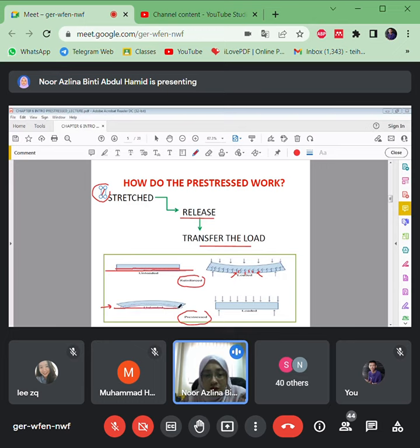We couldn't see it obviously by our eyes, but actually it has a slight deformation from the midspan to the ground surface. It's upward here because of the load that we transferred after we release the cables, that makes this structure slightly upward